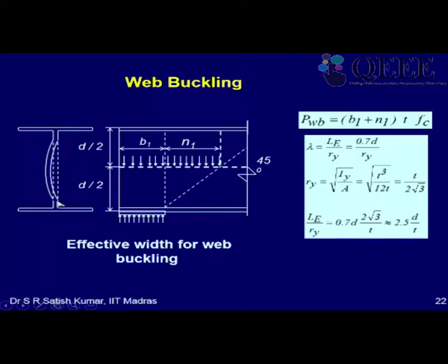It will not be a sudden cut like that, but there will be a gradual change from the web thickness to the flange width. Okay. So that is called the root radius. So this is actually showing you the root radius. But that is not required here. Basically we can say that this is B1, and from here the load gets dispersed at 45 degrees.